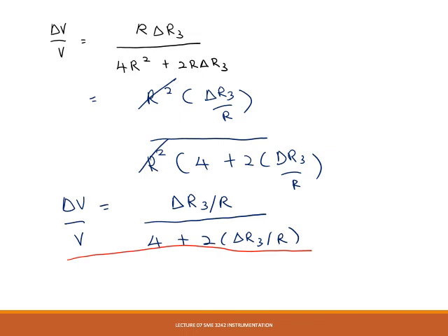So we're going to use this equation whenever the design of the Wheatstone bridge follows our assumption, where R1 equals R2 equals R3 equals R4, and R3 is having some changes. Or it can be any resistance actually. It doesn't necessarily be R3. It can be R1, R2, or R4. But normally we consider R3 to be our sensor.